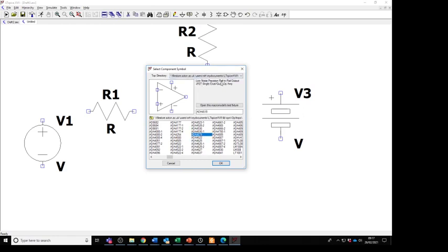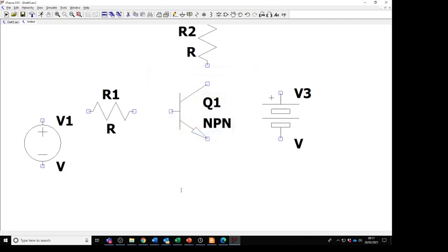This one's a low noise precision rail to rail output JFET single, well, it comes in a pack of 4 sometimes, but they all have slightly different internal performance. So you can model your circuits with particular brands of op amp to see if they will behave differently. Okay, but we don't want an op amp, so we get around that.